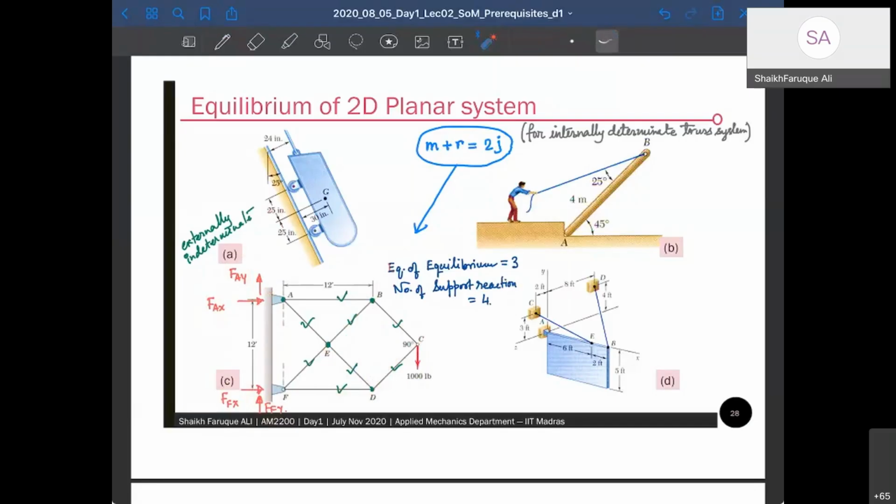Okay, assume there is a roller here. What will happen? You pull this, right? This point will try to move downward like this. No, it will not fall directly. It will go like this. This is also a hinge, so rotation is possible. So this rod will try to go up, and since there is no restriction by this member, it will go up. So the truss will go like this. It will be a very unstable truss. The stability has been gained because of the hinge that we put there. Or else you put a roller here, but you have to put a member here, or a member here. That will make sure the structure is stable.